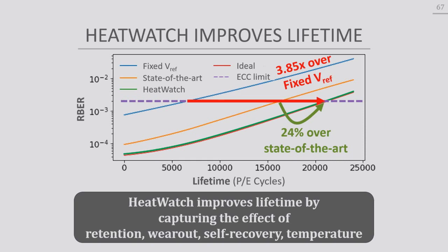Okay. If I go back to this diagram, how many cells do you encode together in a single block? What do you mean? To have a BCH code with distance 40, you have a length that is a few hundred, so you encode a few hundred bits or a few thousand bits together. Oh, you mean the granularity of the ECC protection?